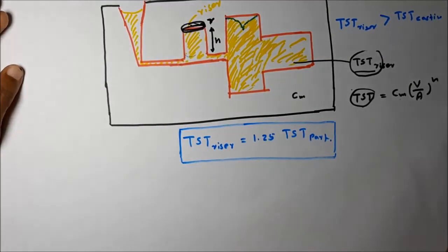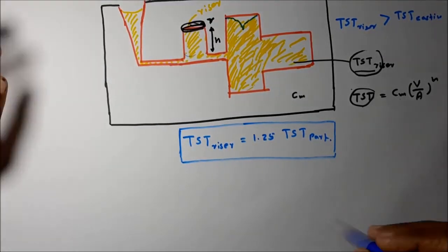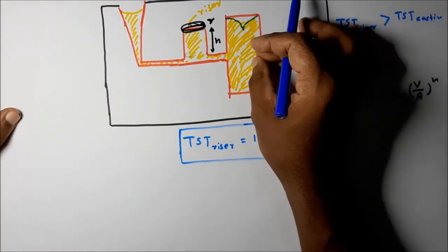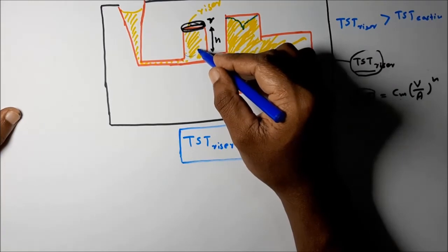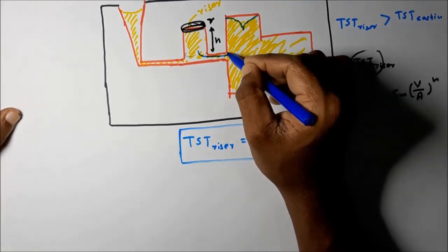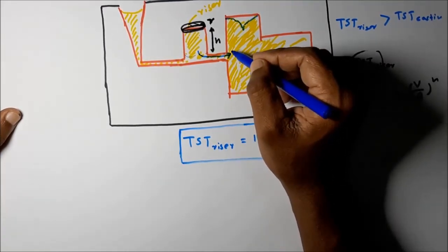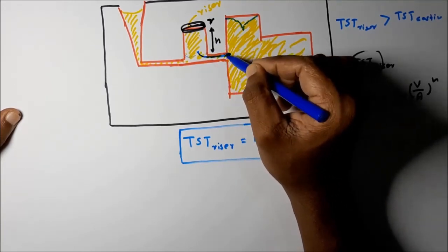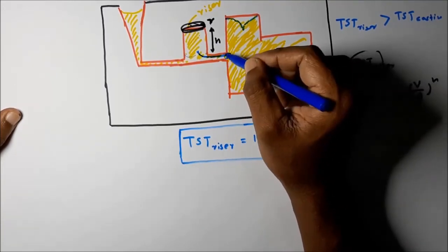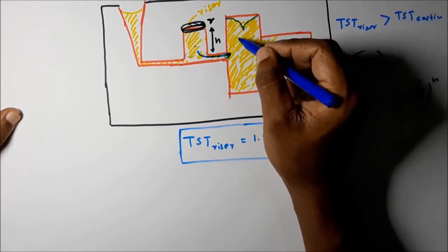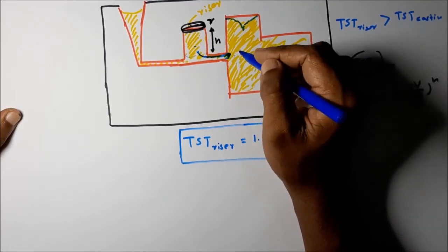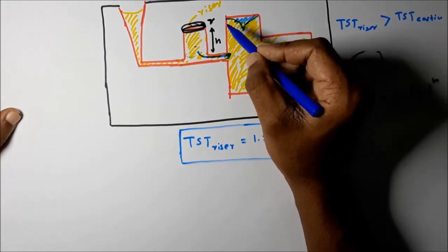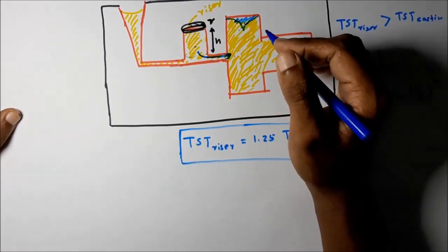After solidification, the lack of volume due to the shrinkage of the part can be fed by this riser through this runner. To compensate this lack of volume, the riser can feed molten metal, because it keeps the molten metal. This is how the shrinkage cavity defect in metal casting is avoided using risers.